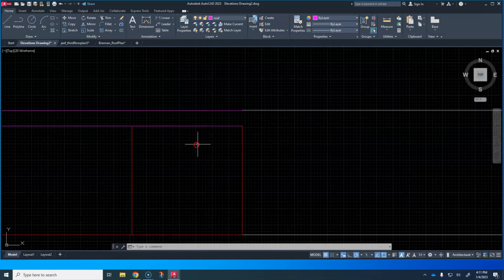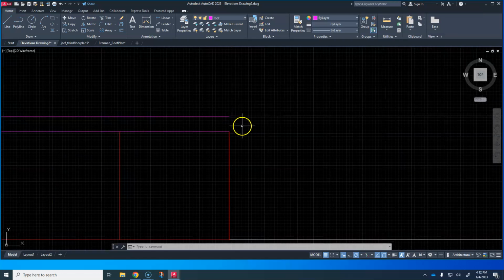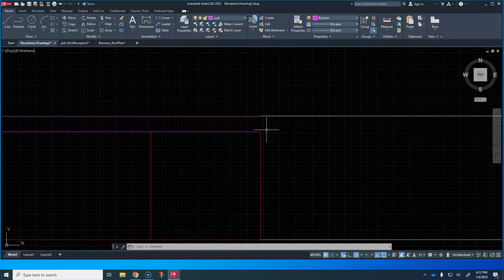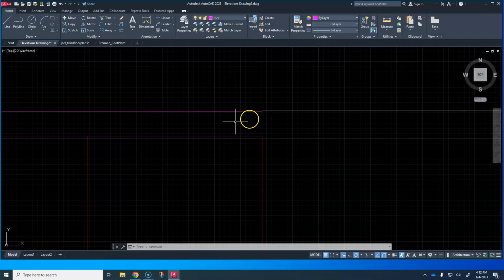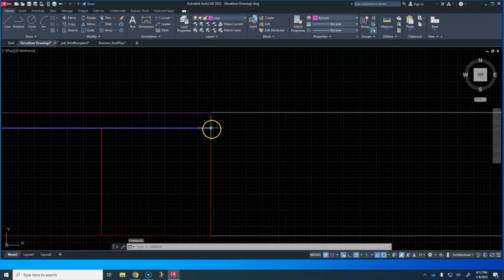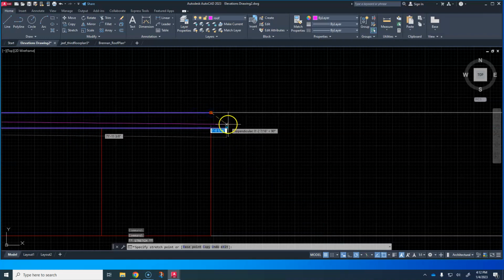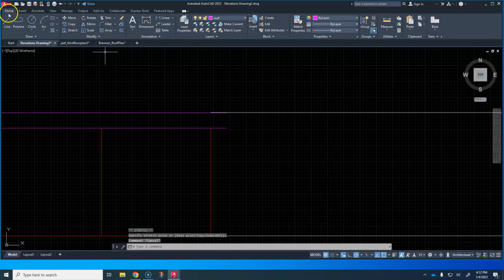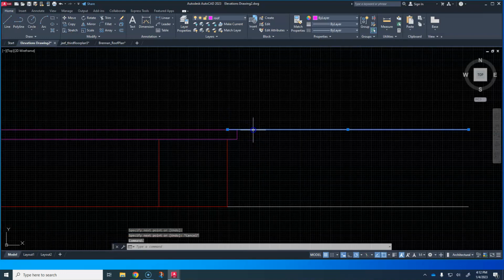I'm going to do the same thing over here. Now, fortunately, our top of wall level almost comes out the same, or it really should be the same as that wall level, just based on the geometry. So that's a good thing that gives us a little bit of reference. Okay, so I'm going to extend this one 1 foot. And then I'm going to match this one to that, get some referenced geometry, and there we go. Draw a vertical line straight down, or straight up. Okay, and I'm going to move this over to the side just a little bit.